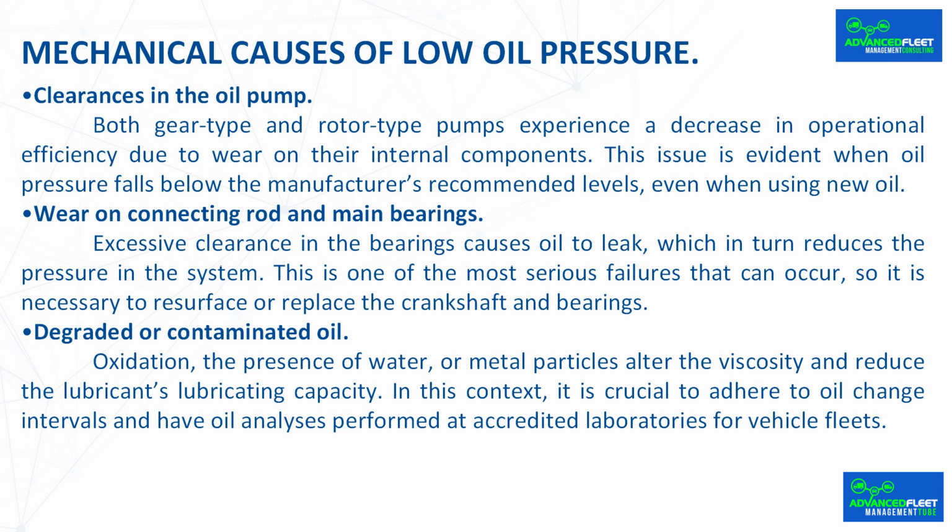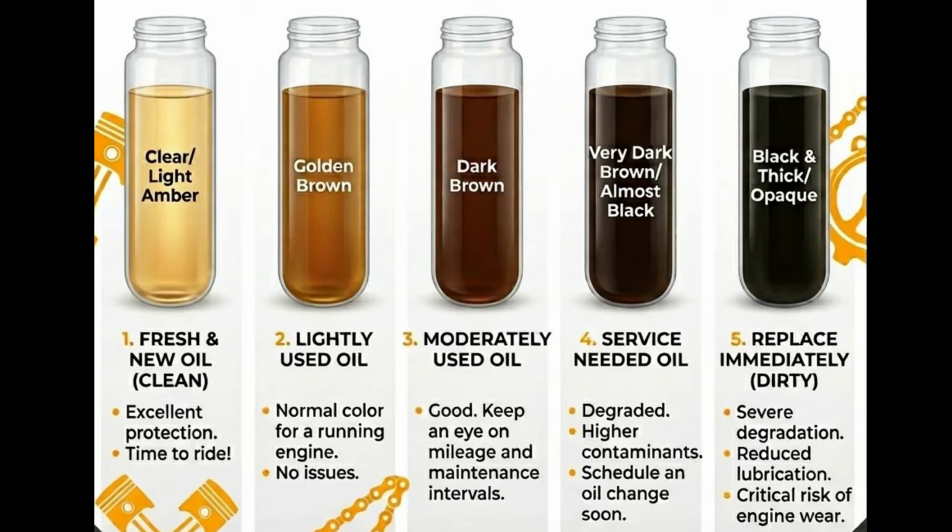Excessive clearance in the bearings causes oil to leak, which in turn reduces the pressure in the system. This is one of the most serious failures that can occur, so it is necessary to resurface or replace the crankshaft and bearings.